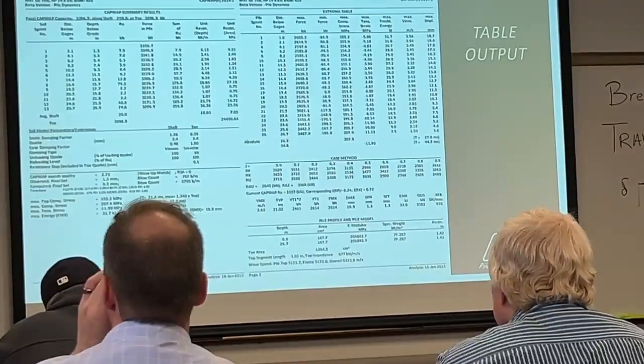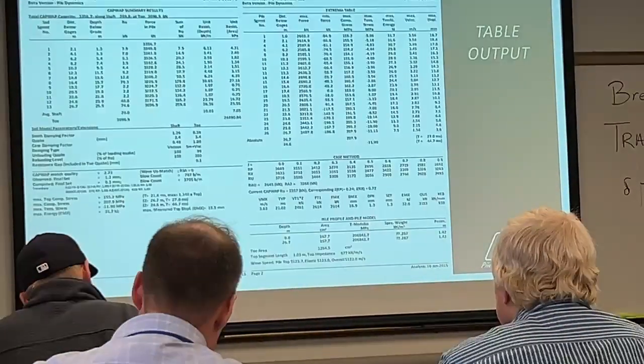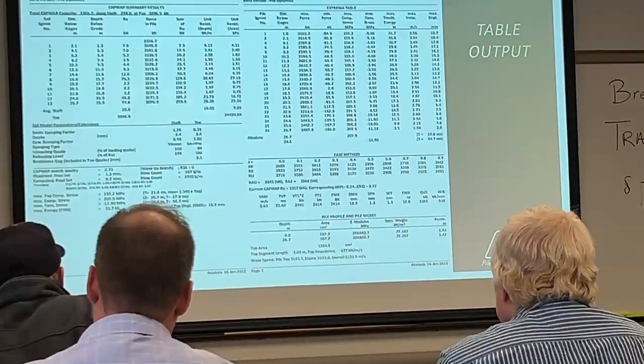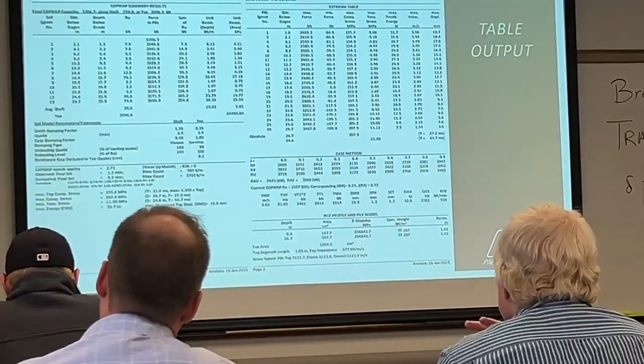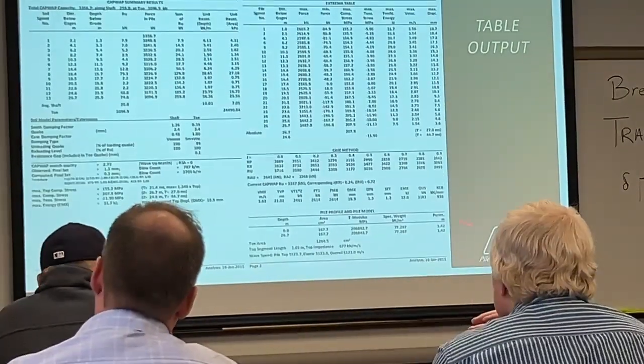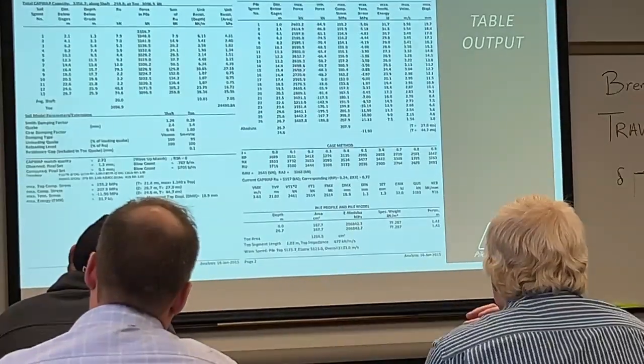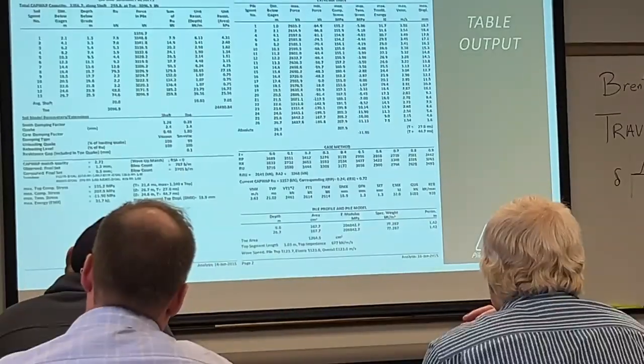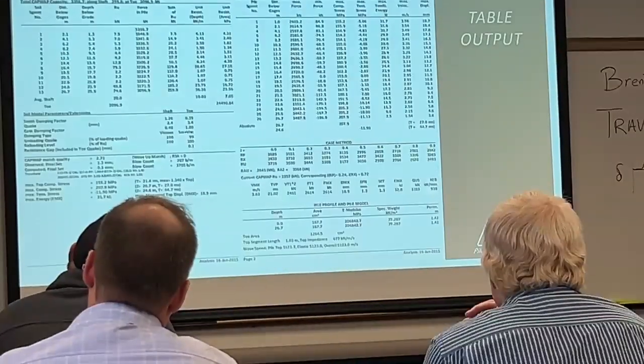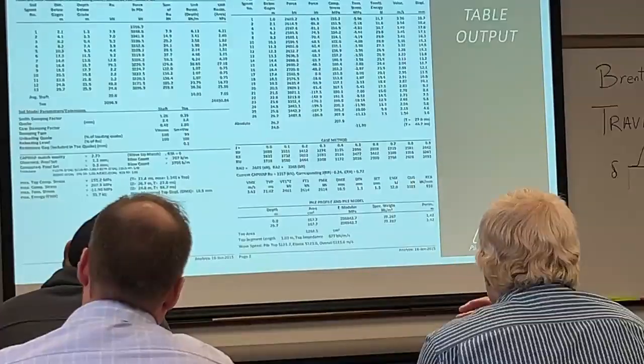The maximum compression stress can occur anywhere, and in this case is happening at a depth of 26.7 meters, which is the bottom of the pile. Do we expect high stresses in a pile that has been driven to rock at the bottom? Yeah, we do.